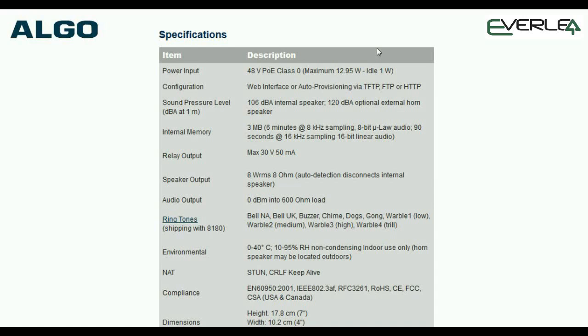because post-deployment, suddenly a phone starts playing up, or an Algo 8180 restarts for any reason when you're paging. 99.9% of the time, that will be your problem. The PoE switch is under-spec'd.